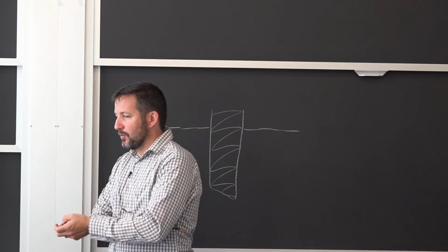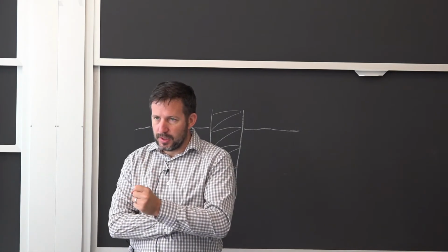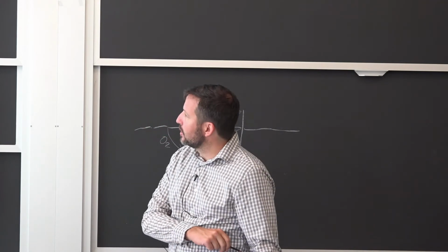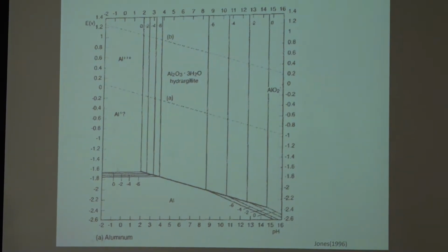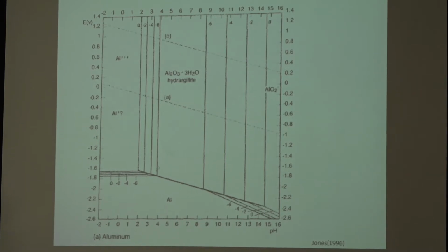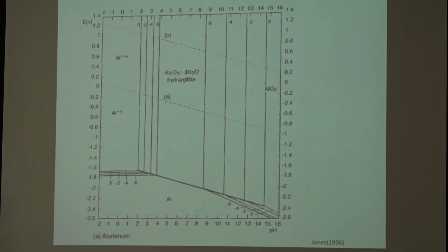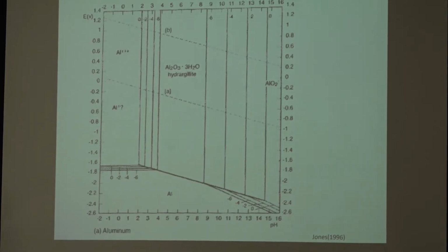Very good. So the question was exactly what I was trying to answer, but I didn't explain it well. Aluminum generally doesn't have a corrosion issue, because normally it's in zone B here on the screen. It's in the zone of stability of that alumina layer. But if the x-axis here is the pH, if you move out of a pH of about 3 to 9, you lose that stability. It's not anymore the alumina that is the most stable oxide, and those other oxides don't form a very good surface that is protecting against corrosion anymore. So it's not isolating the substrate, and in those conditions you have accelerated corrosion.